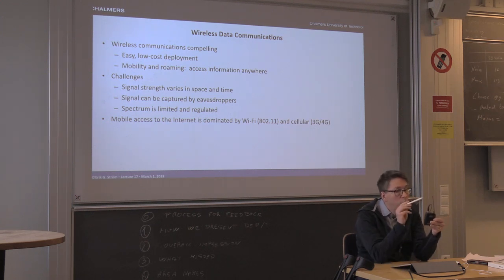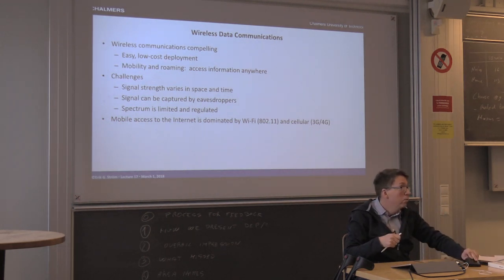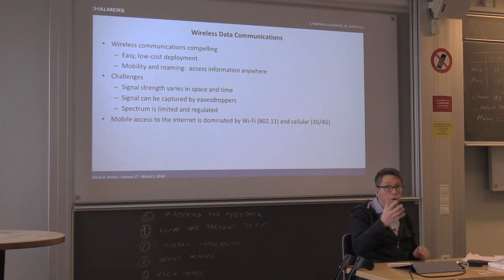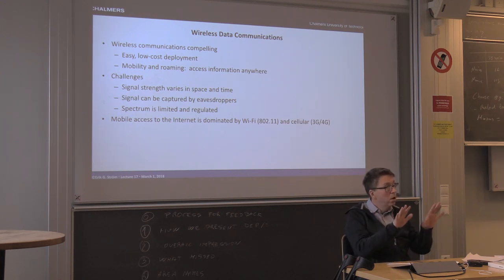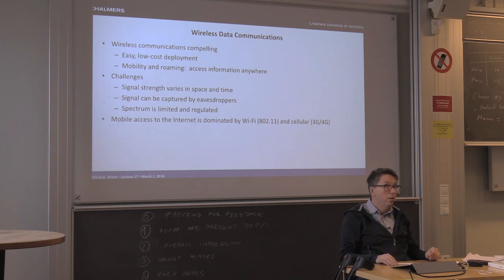And also another problem is what's called multipath propagation. So the signal that goes from this microphone to the receiver takes the direct path between them, but also is bouncing off walls and so forth. So that creates a distortion phenomenon called fading, which could be quite severe actually, because at the receiver you receive multiple copies of the transmitted signal. Sometimes these are adding constructively and sometimes destructively. If they add destructively, it means that the received signal strength could be very much weaker than the path loss alone would dictate. So there are many problems with this.